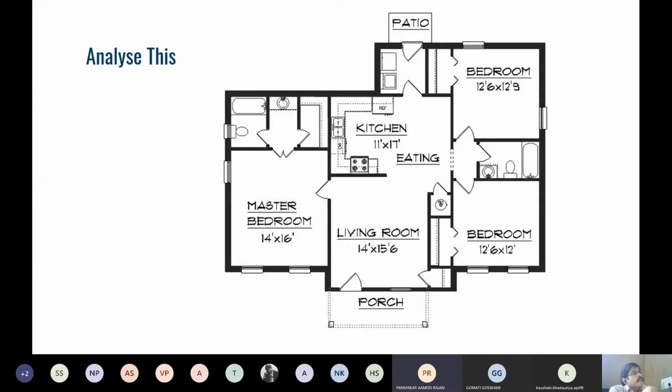You give a source of sunlight in your drawings. So we should be able to know where the sunlight is coming from, right? How do you know that? Sir, directions are missing. The directions are missing. So direction. Any type of drawing you do, this is the first thing which should be there. This is again part of the architectural design, the orientation. You should always mark your north within your drawings. Always. Whether you have been told to or not told to, the plan should always have a north.